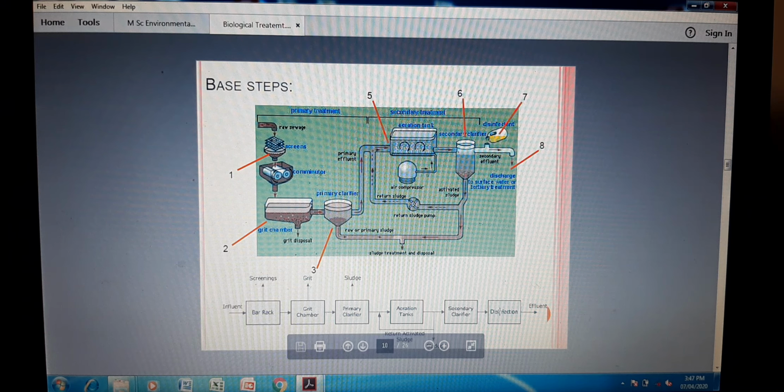So in that tertiary treatment, it is disinfected. Then treatments like the membrane bioreactors can remove the sludge, or remove the color, and lastly the odor. After the tertiary treatment, it is disposed on land as well as into running as well as stagnant water bodies. So in this particular overall